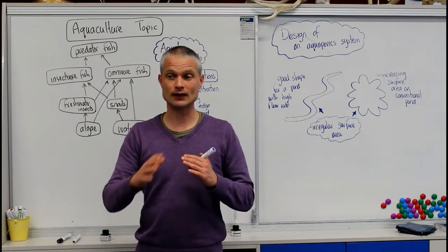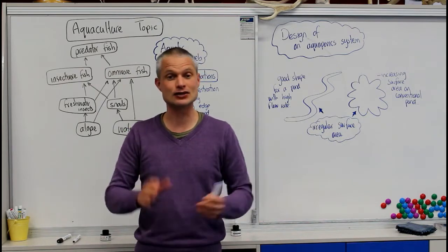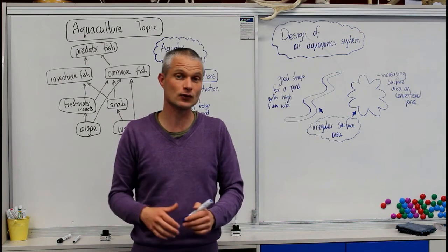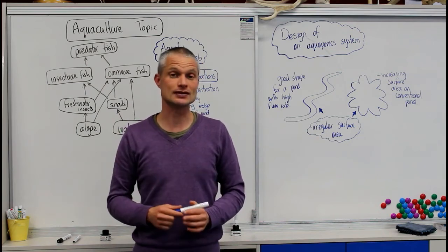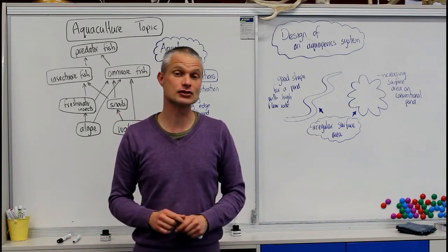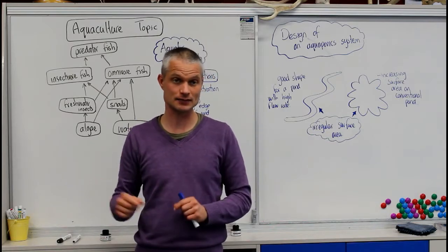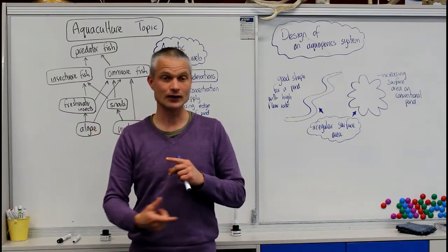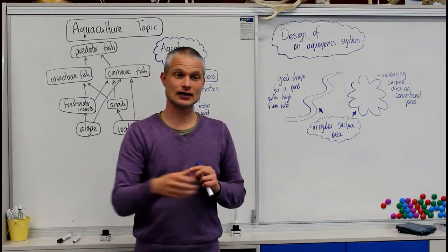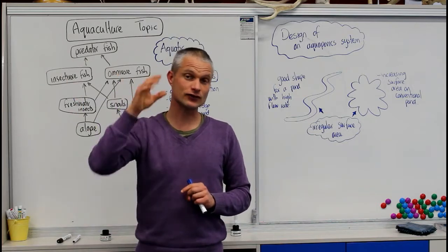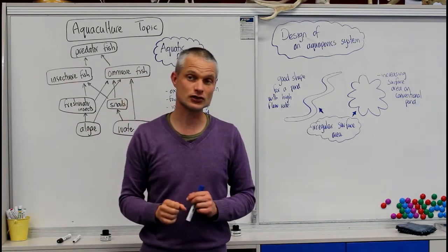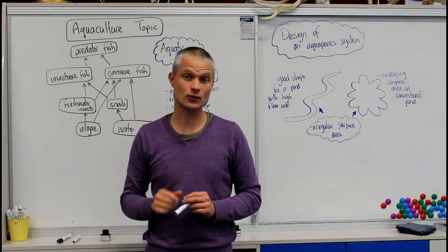So if you plant out along the riparian edge of the pond, create a bit of shade over that water, that will help cool the water down and lower the temperatures, in addition to creating a circulation of water in that system to help create a flow of water on the surface. And it's on the surface of the water which is where the oxygen is dissolving into the water and dissolving out of the water.